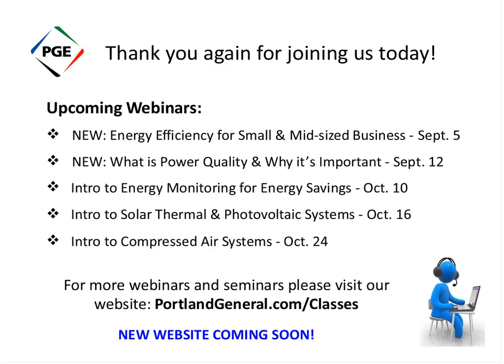Okay, the different options for T12 fixtures. There's actually a lot of options, which is a good reason to come to the seminar next month. But in general, obviously you're going to need to change the lamps and the ballast in a retrofit. I highly recommend changing the lamp holders, even though you could use the existing ones.